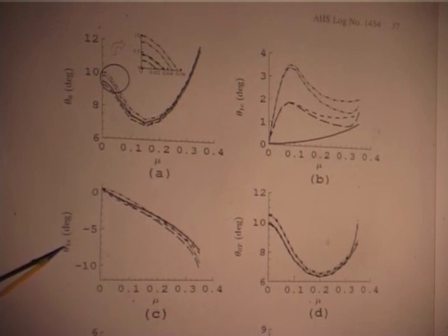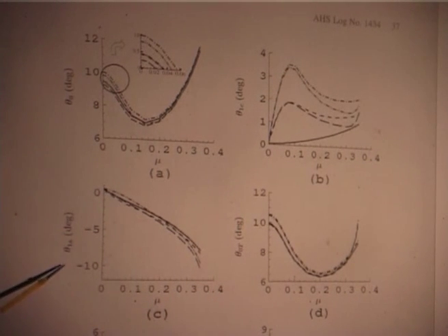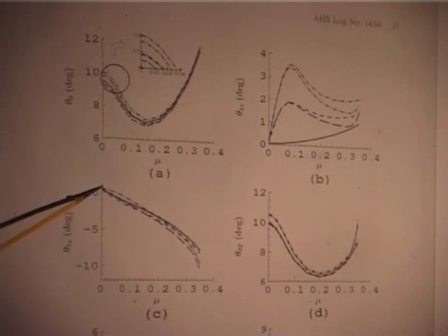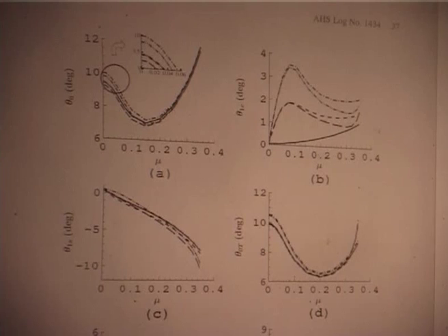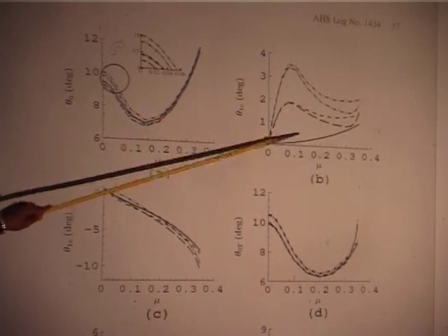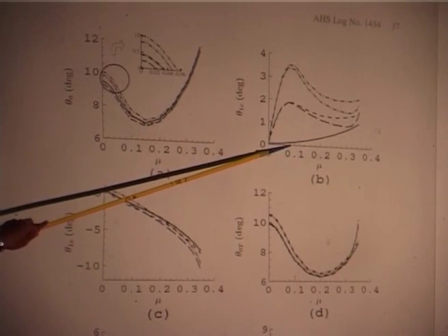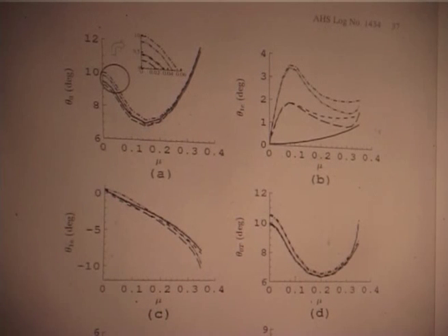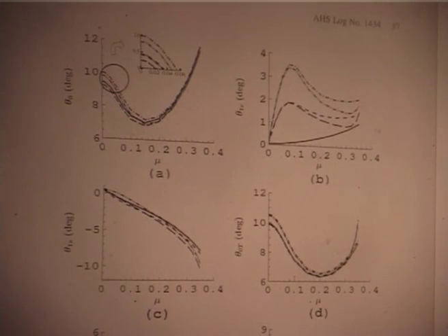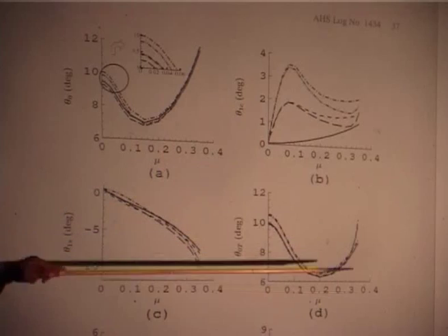And of course, you see theta 1S, that is the longitudinal cyclic, you see this is negative, okay, and that keeps increasing. These are with the different aerodynamic models. Now, here is theta 1C, which is the lateral cyclic. With the different aerodynamic models, I am getting different curves. This is the uniform inflow curve, the lowest, that continuous line, and I have included a dynamic stall model and dynamic wake, some additional more complex models. You see they change drastically, okay, just in equilibrium.